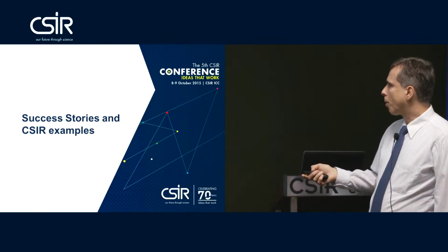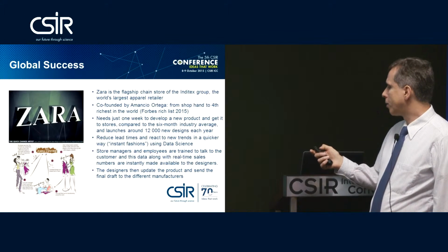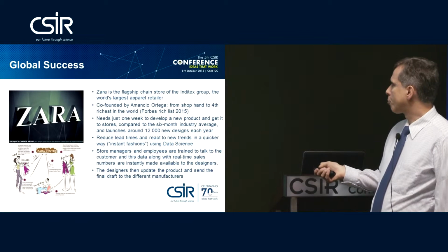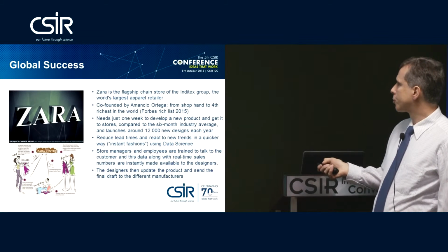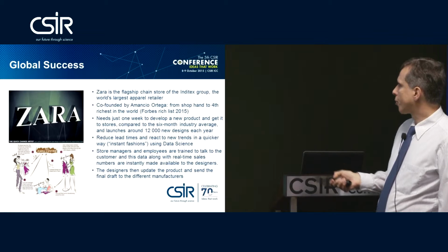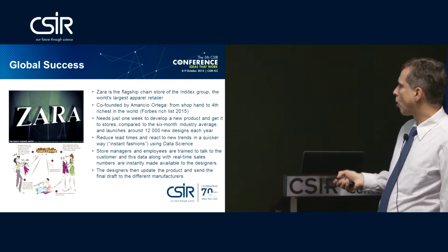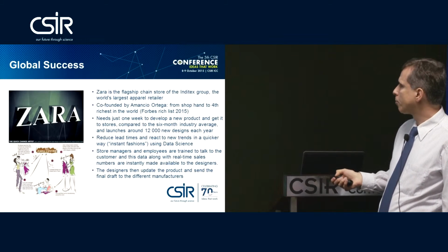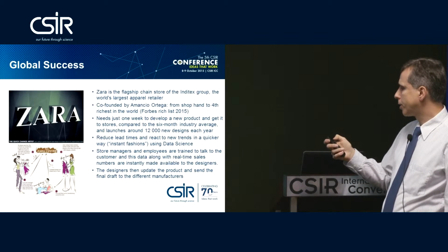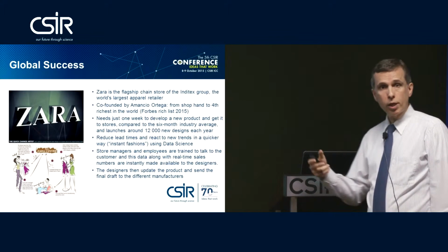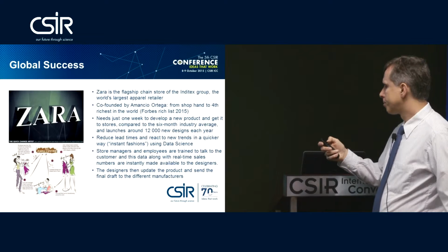If we move the robot, we can then do another scan. Here it is at point B. Again, it's facing in the direction of this red arrow, and it scans 360 degrees around itself, and it finds some walls. Again, it can't see around corners, so there's some limit. We have a partial representation of the environment. And what we'd like to do really is put these together and